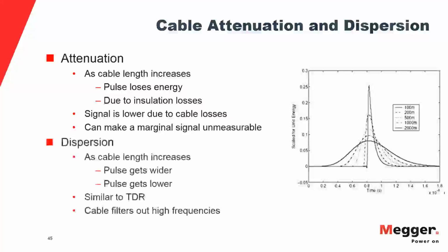We also have our TDS 40 and 60, which does testing up to 40 or 60 kV. And this unit has damped AC and cosine rectangular built in. It's suitable for PD diagnostics and VLF withstand testing. We have a unit called the TDM 4540, which combines the best of both of these. So we have damped AC, cosine rectangular, and sinusoidal all in one unit. This tests up to 45 kV peak, and this is suitable for all testing, PD, tan delta, VLF withstand testing, and it is modular, or you can add on to it. You can start with the base unit and add parts to it as needed.